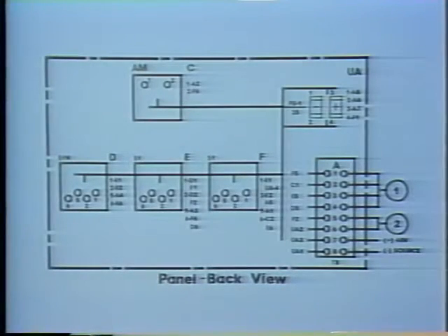Another important aspect of a connection diagram is the component identification. Components are usually identified by letters, and they're usually listed alphabetically, from left to right, top to bottom, starting with A and then continuing through the rest of the alphabet. If a unit has more components than the letters in the alphabet, then the designer will use two letters such as AA, AB, and so on.